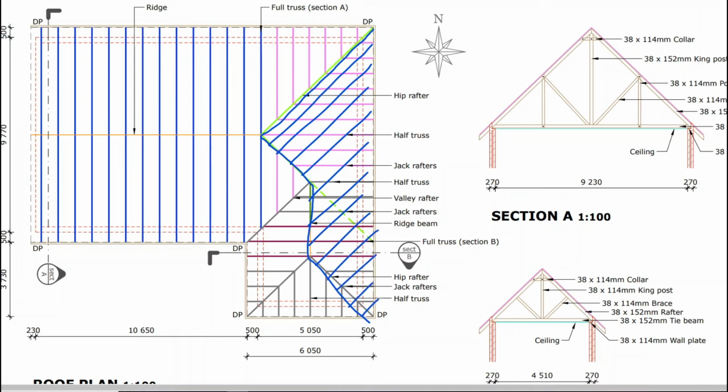Because if you don't see the faces, it's hard to tell, for instance, what is this? Is this a hip rafter or a valley rafter? This one. Well, okay, obviously this end is a hipped end, so you got 2 hipped rafters there. But this basically decides how many purpose-made tiles you're going to use.